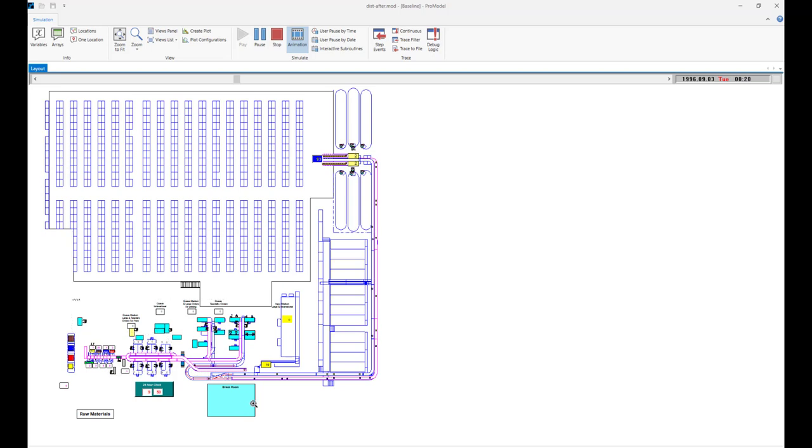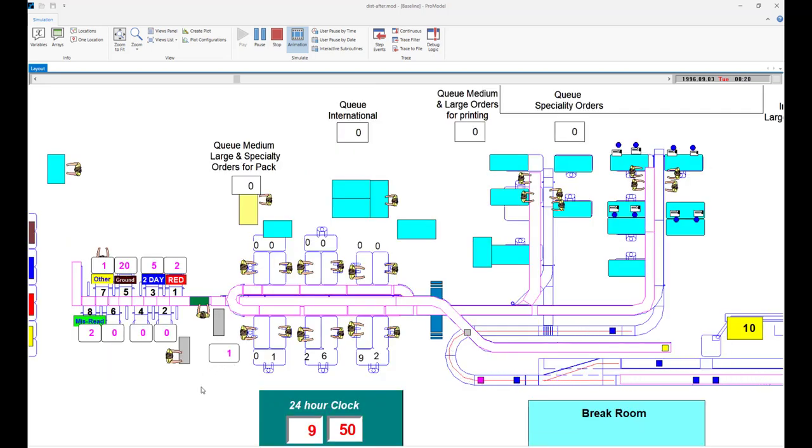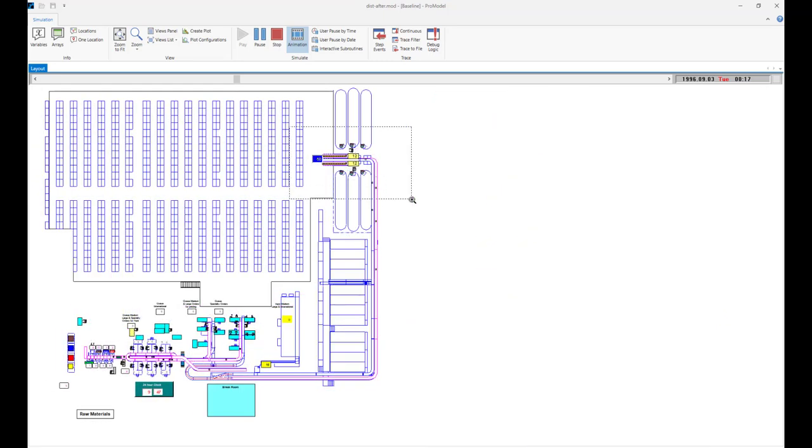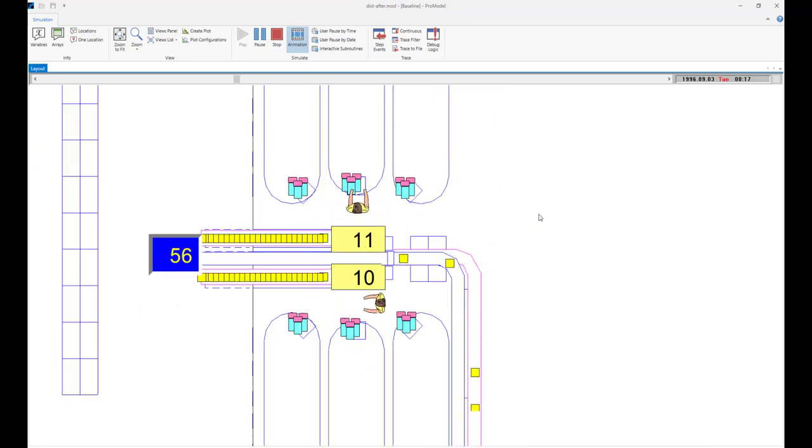As a result, they immediately implemented the change in their WMS system and saw a daily system throughput increase from 5% to 14%. However, they still were unable to fill all the orders in a shift. In studying the data provided by the new model, they were able to identify the next areas that they could change to increase throughput. The model showed that with the new tote induction locations, the bottleneck was shifted from the conveyor system to the print pack area.